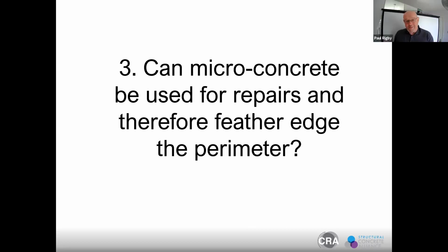Right, the short answer on that one is yes, it certainly can. Microconcretes can be used very successfully in shuttered environments because obviously they are fluid materials, generally where you've got congested reinforcement as well. Over a metre square, I'd consider using them. Feather edging in any repair situation is not ideal because the feather edging becomes a sort of planar weakness. So I'd always try and work to a well-prepared edge, which can be difficult in some situations, and I'm sure Richard might want to come in on that and back me up on that maybe.